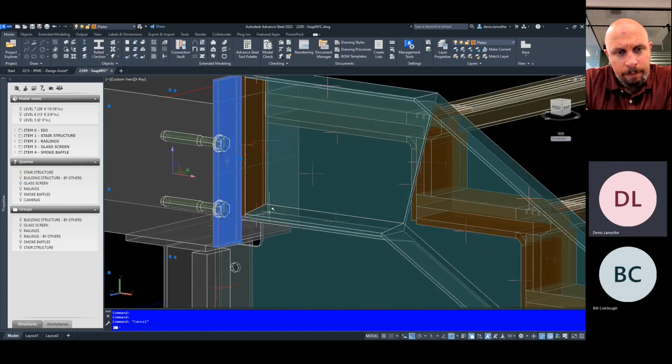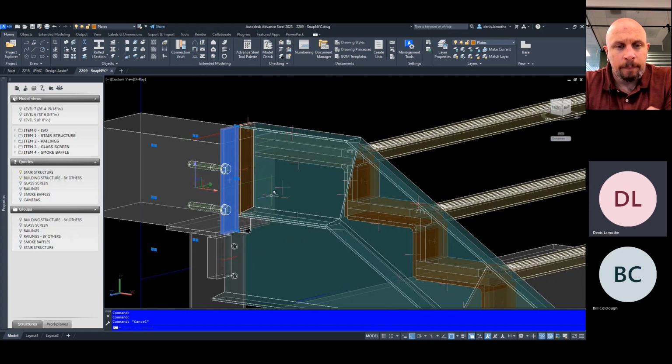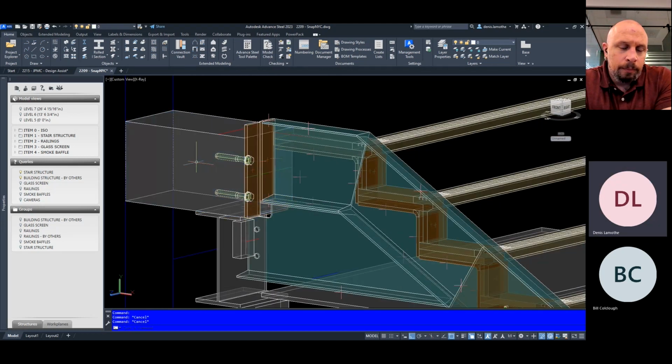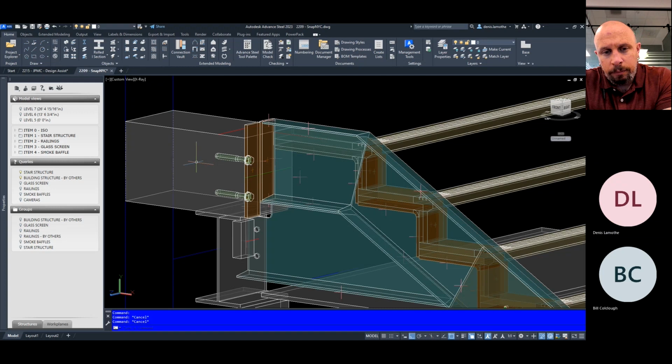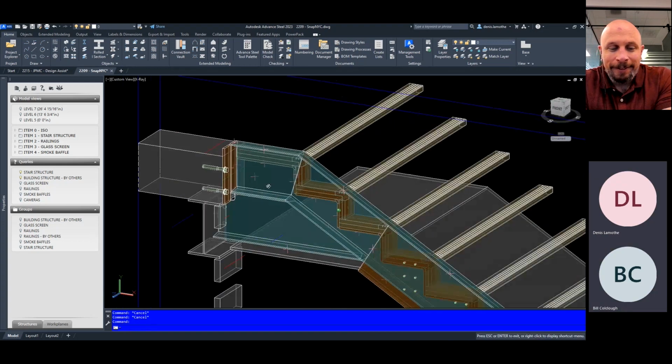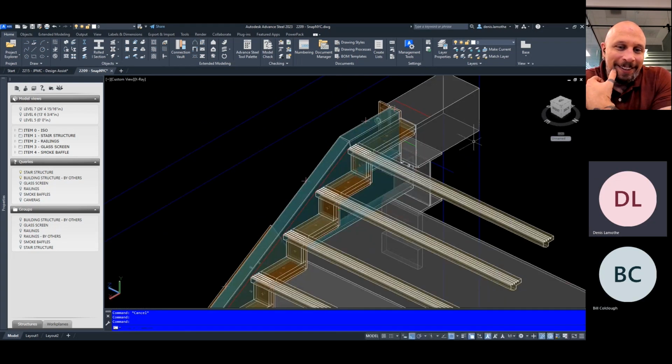It might look something similar to this, but on the inside part with your anchors going into your concrete. And again, those only work if we're not messing around too much with rebar or especially post-tension concrete floor slabs. The engineers, I wouldn't say panic, but look at it as kind of funny if we make that proposal that, yeah, we'll just anchor in a PT slab, and if there's a post-tension rod in the way, we'll just cut it. Oh. We don't do that. We avoid that. We don't want to give them heart attacks.